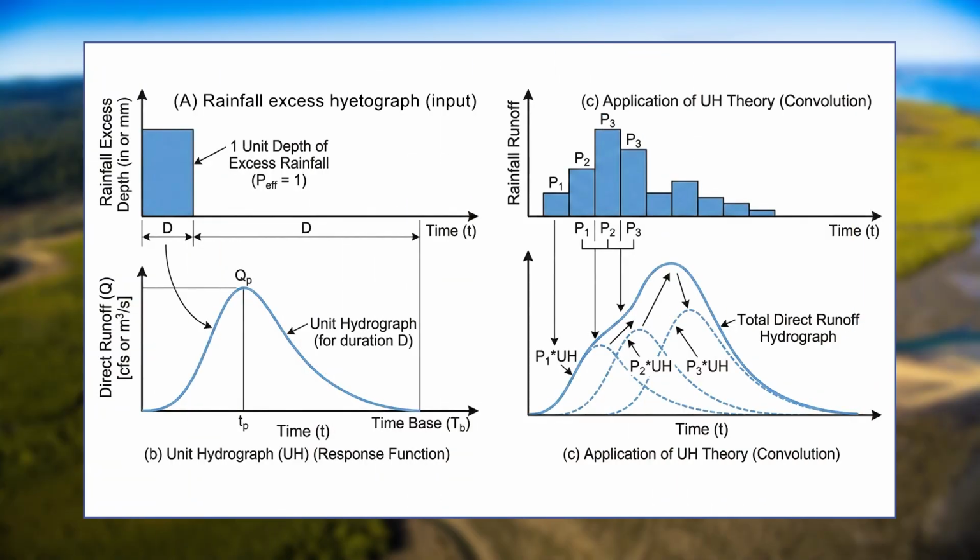Models like the Hydrologic Engineering Center Hydrologic Modeling System mainly predict peak flood discharges, while SWAT is applied in semi-arid watersheds for soil moisture, flood and drought management. Another method for modeling the direct runoff response from rainfall excess is the unit hydrograph theory. It is a vital technique for predicting monsoon-driven runoff and floods. Similarly, the Soil Conservation Service curve number method is extensively applied to quantify runoff volume.